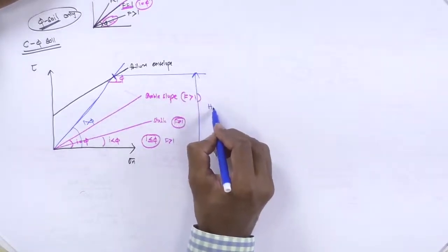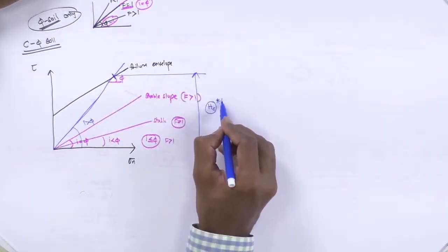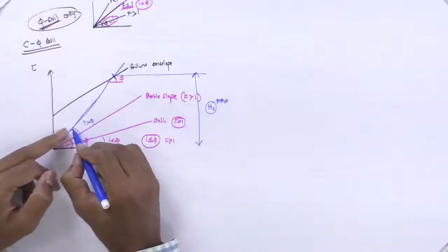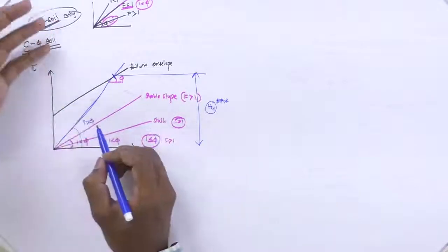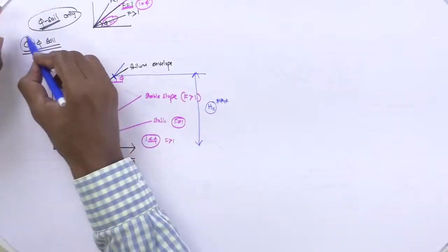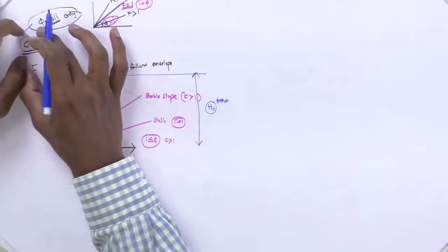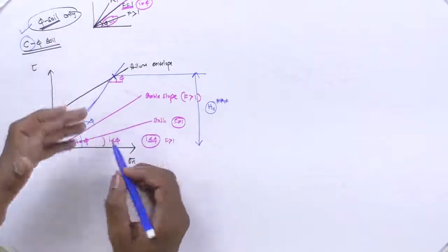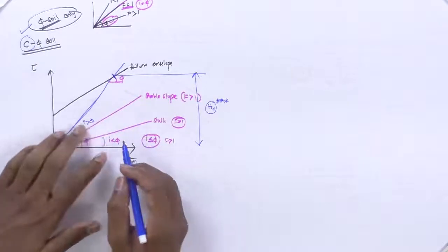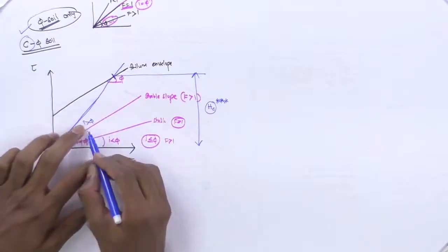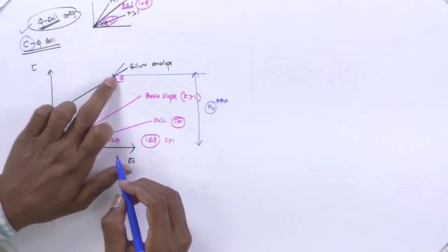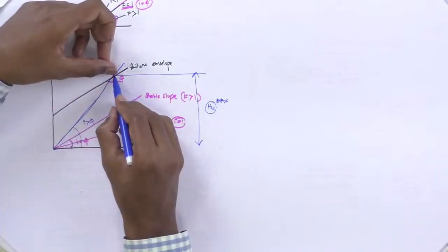This height is known as the critical height. It is a very major point to be noted. Critical height means my slope can be greater than phi for cohesive soil. In the case of cohesive soil, cohesion helps the soil to go beyond the phi value. So I am increasing the slope inclination beyond phi, and by the way I am going, it meets this failure envelope at some point.